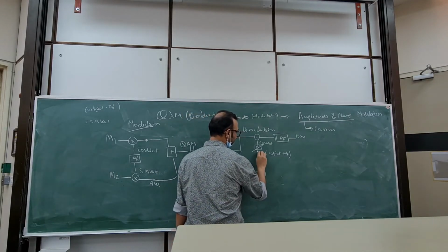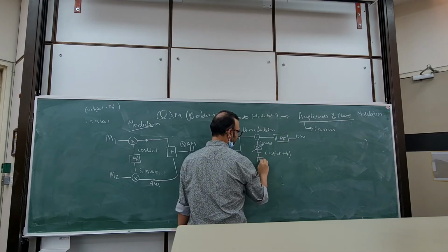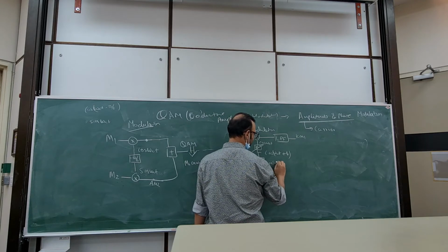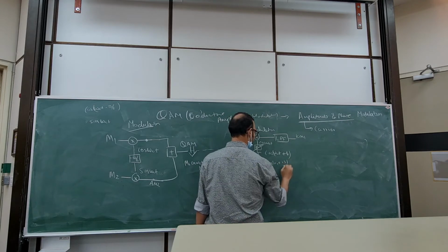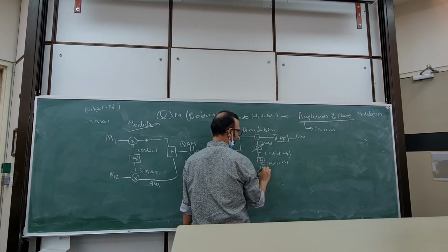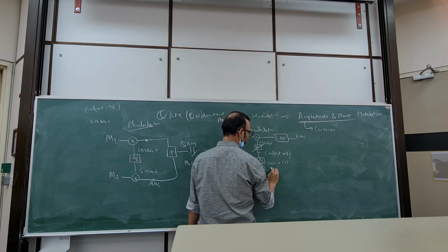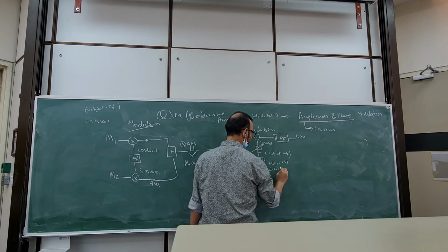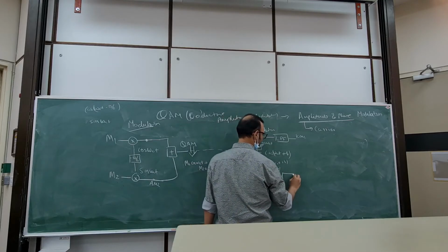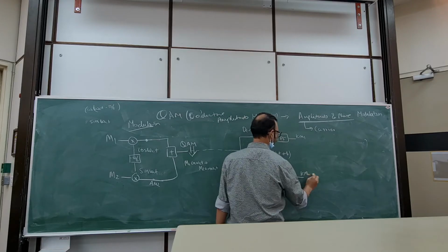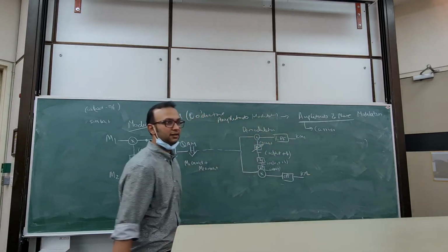Same thing, multiply, but this time by minus pi by 2, so that you have sine omega ct plus phi, and again there is a phase shifter here to give you sine omega ct. Then that goes to a low pass filter, and this becomes a scaled M2.